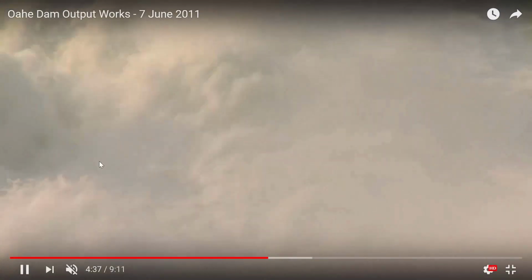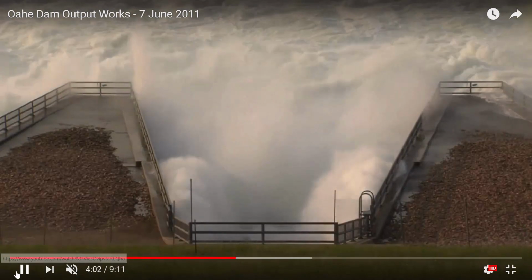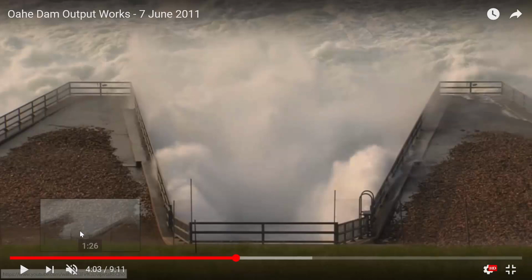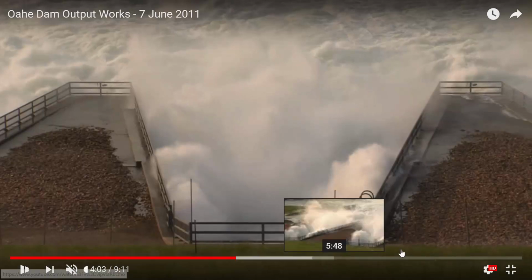So back to the shape of these, it is gradually expanding. What's the velocity effect of it gradually expanding like that? It's intended to slow it down. So we start with this narrow diameter where the velocity is going to be high, and then as it widens, the velocity decreases. Now, it's not going to decrease very much when it's got this much momentum. But under lower flow rates, the velocity decrease could be more significant because there isn't going to be quite as much momentum as we see exiting right now.